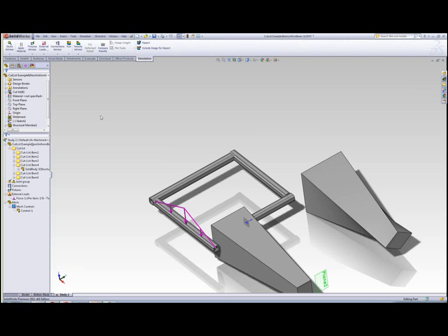Also, let's talk about results. Nonlinear plots. You can now plot elemental or principal strains for your nonlinear plots. Just the way you would do that, you would right-click and edit definition. You would be able to see and select the first, second, or third principal strain inside of our components. I think I said stress there by accident. Excuse me, it's strain, principal strains.